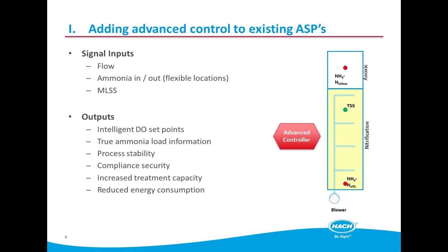Then you have an estimate of the sludge age. So of that biology, you know that X% will be nitrifying bacteria. That allows you to know how hard you've got to work those bugs to make sure that you're achieving the right level of treatment. So the controller doesn't alter how the bugs behave. It follows what the bugs are doing, so the biology determines the rate.